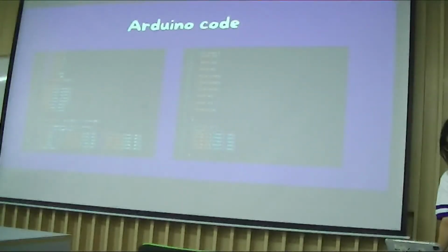And this is the Arduino code. We first start with this file to define the pin numbers for the LEDs and the switch. For on and off, we define them as HIGH and LOW, which is how Arduino programming sets the pin state. And then we have the message array, where we can store up to 10 messages.